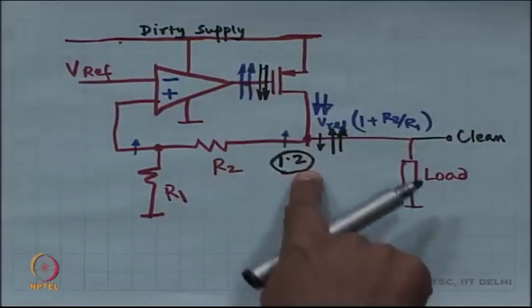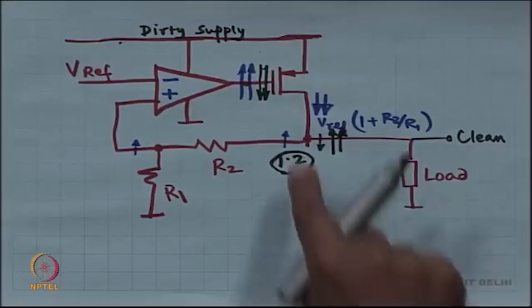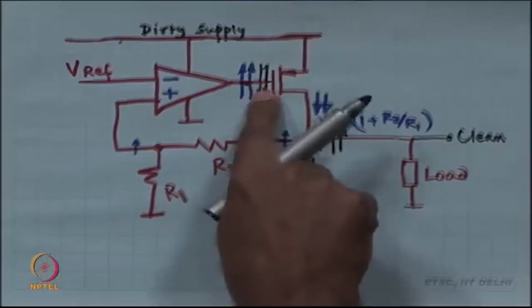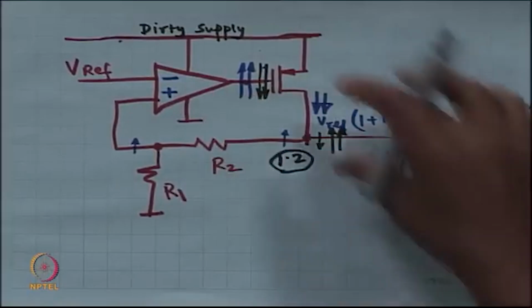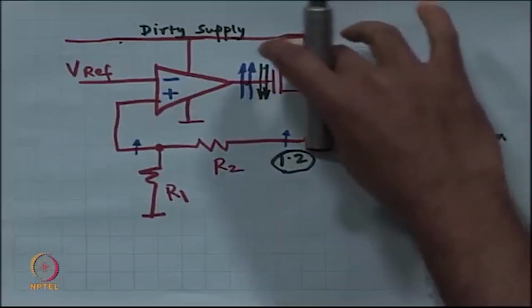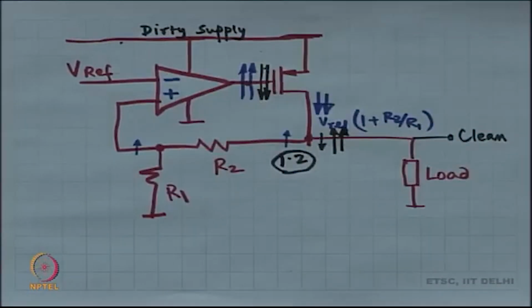Is the value of the gate voltage related to the drain? No. For example, the drain of this PMOS can be higher than the gate voltage, it does not matter, as long as the drain to source is more than source to gate minus V t. So, typical source to gate minus V t, VGST, is typically 0.2 volts.